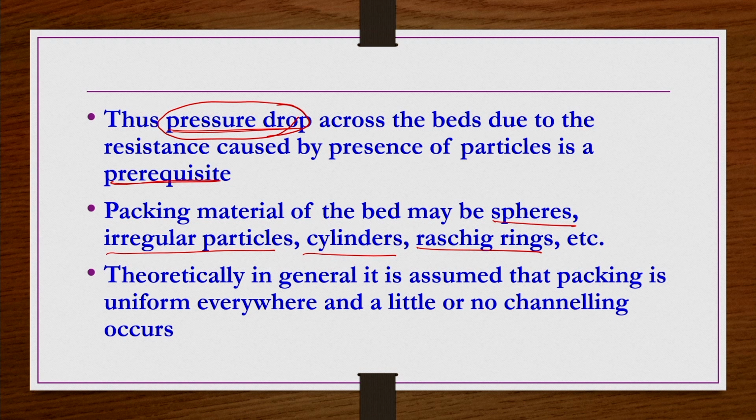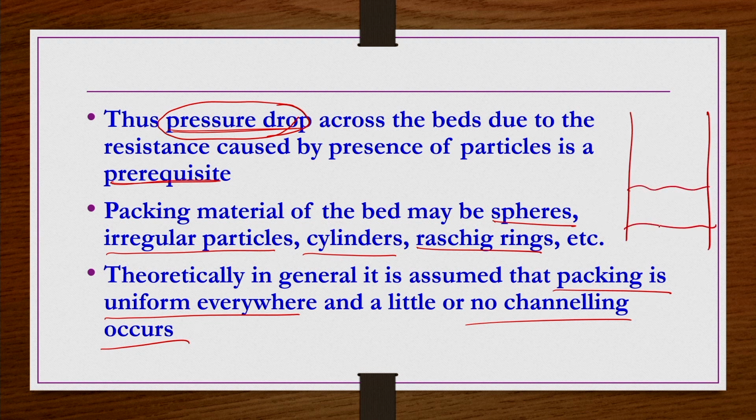But theoretically, what we assume, and in whatever analysis we are going to do, we assume that the packing is uniform everywhere and there is no or little channeling. Channeling in the sense that the bed is there, let us say this is the bed. Within this bed somewhere you have channels which allow the fluid element to flow through without any kind of hindrance. So, particles are being segregated and forming channels, right.